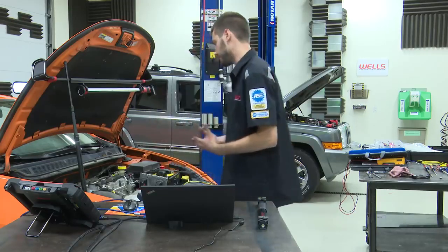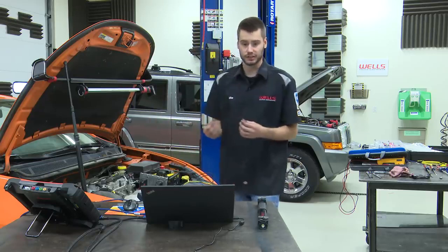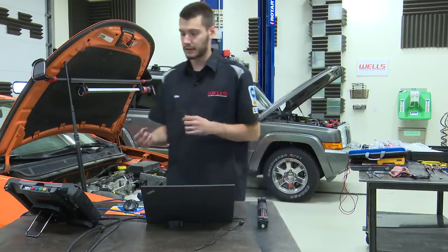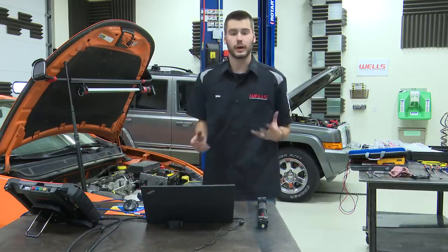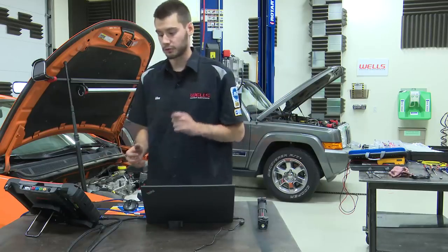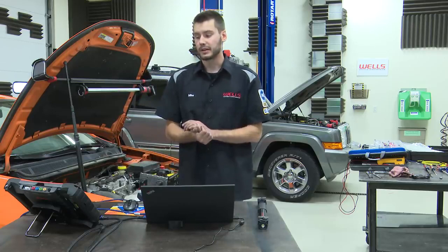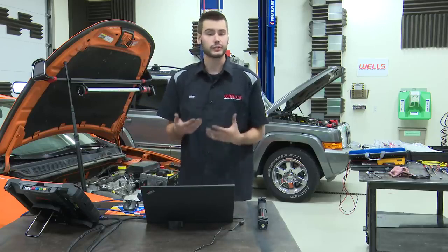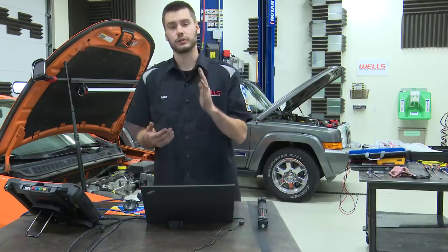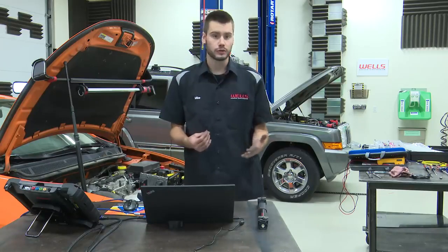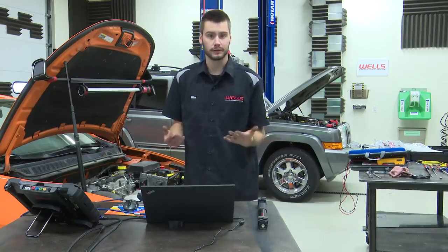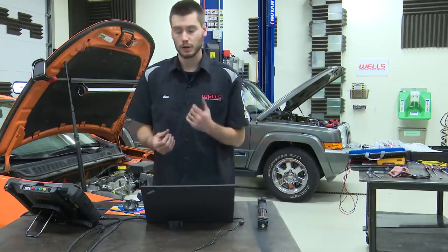If the alternator is having to charge a lot, you'll see different throttle positions spit out in your PID data, where on a vehicle like this Jeep, you should typically see your throttle position right around that 0 mark. Because the idle air control valve is doing all of that work, your throttle plate is going to remain closed until you, the driver, step on the gas pedal, okay? And you actually pull it open with the cable.